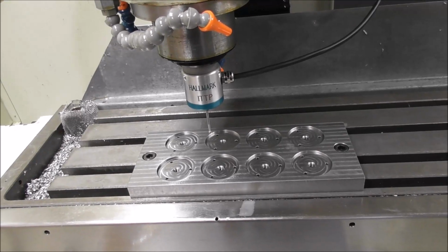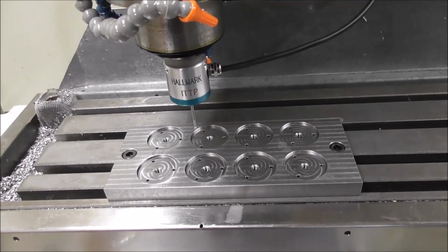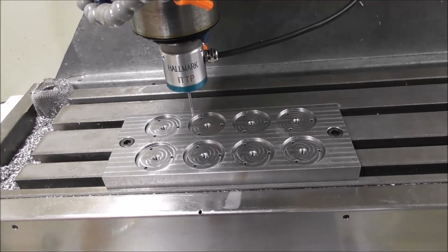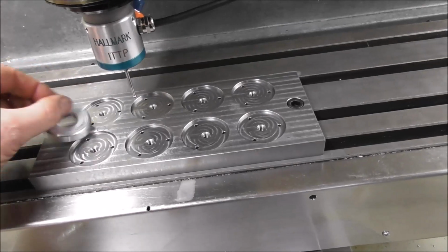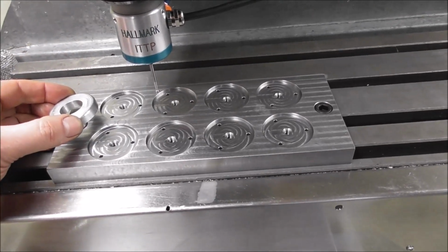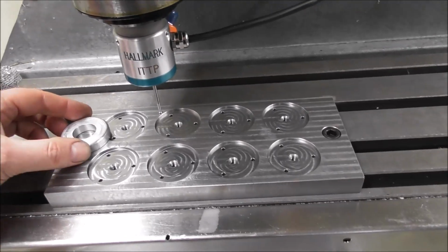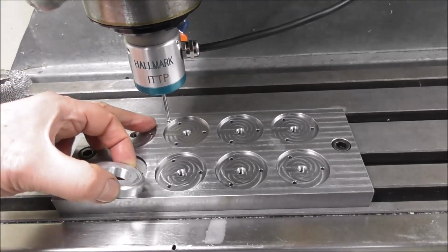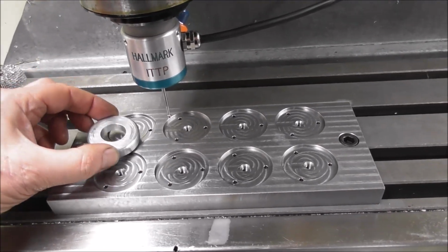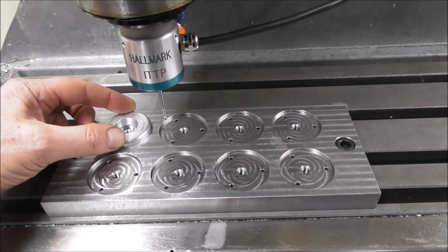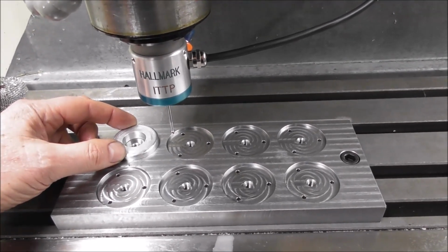I'm just going to use my probe. There's other ways you could do this because they're of a certain pitch and you could enter the values, but this is quick because it's an impact tolerant probe and I can just zoom around with the probing routine and quickly set those 8 different positions. So I could set them straight in the little recesses, but I'm going to use this sample part which I use for setting because it also sets the Z height. So I'll just go around and quickly set those.